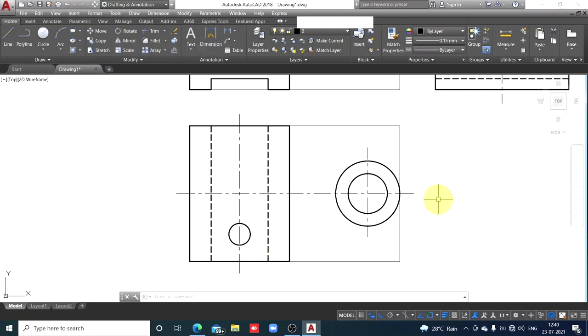This is axis of symmetry, but this circle we can draw it here independently also, like we measured 15 millimeter from front end by measuring 15 millimeter from back end to locate the center. But since we have just started studying AutoCAD, I am just introducing you different commands. Before that, the circle will complete. What's remaining in the circle? Center line, the horizontal center line.